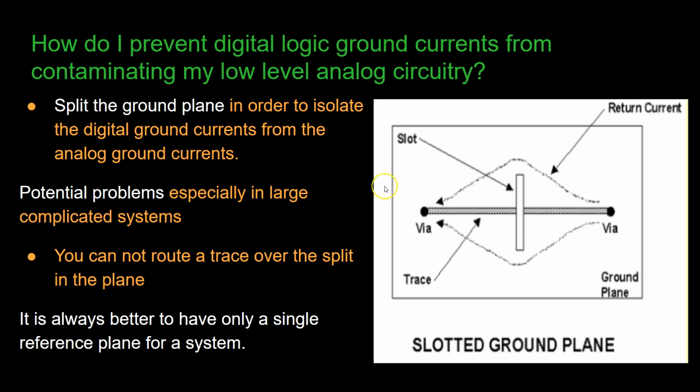And also, the ground planes solve many ground impedance problems, but not all. Even a continuous sheet of copper foil, if you use it as a ground plane, will have some residual resistance and inductance, and in some circumstances they can be enough to prevent proper circuit functioning.